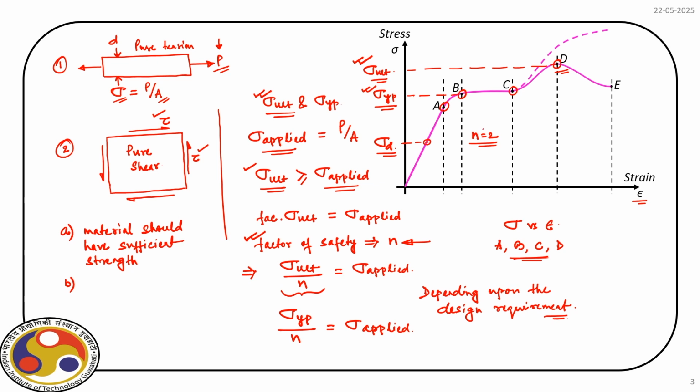we cannot arbitrarily apply this factor of safety. There are certain guidelines based on another fact is that we also should consider the economy, because if we increase this factor of safety, obviously we can sense our structure will be safer, but in that case we do not utilize the material property fully. Although these are not the aspects of our discussion in this course, but the fact is it all comes from the stress strain behavior of the material.